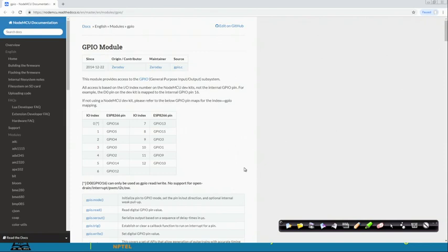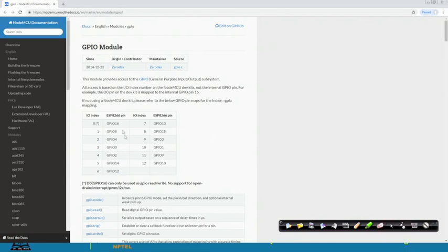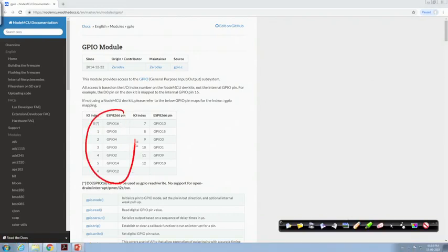These are the different mappings between the IO pins and the GPIO pins. So, this is basically the pin configuration and the mapping between the regular IO pins and the corresponding GPIO numbers, right. This information will have to be taken into consideration while trying to map between the GPIO and the pin numbering in this NodeMCU board.